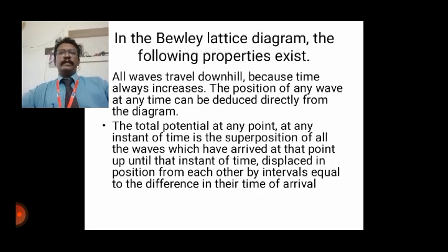You can see that normally this kind of diagram straightaway conveys how it is related with the parameters depicted in the diagram. Take a voltage source, particularly a surge of magnitude unity, which reaches a junction between two sections with surge impedances, normally named Z1 and Z2. Then part is transmitted and part is reflected back, which actually happens in high voltage surges.